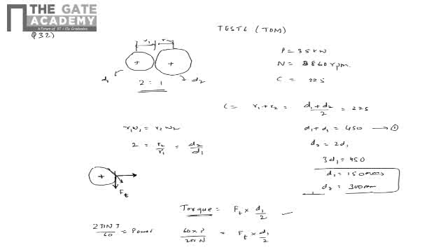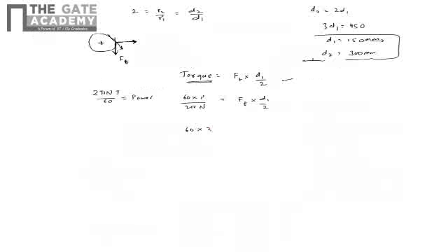So when I feed in all this information, 60 times power 35 kilowatt per 2 pi, speed is 860 rpm, is equal to Ft. Getting the diameters is useful here, so 150 by 2, probably we need to write 0.15 since it's in mm. Everything we are keeping in meters.